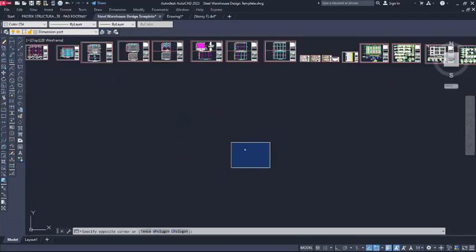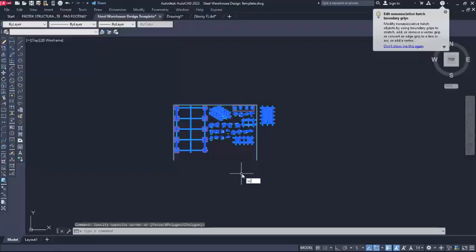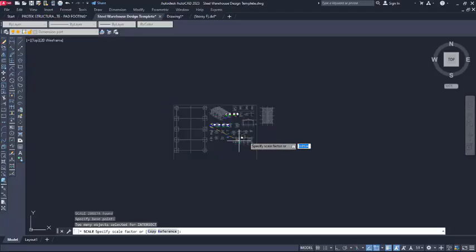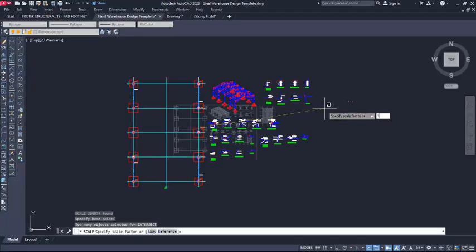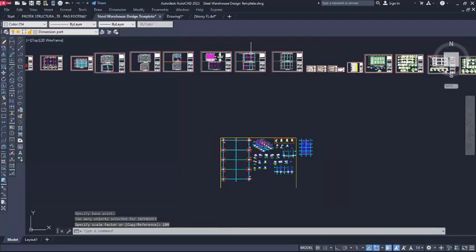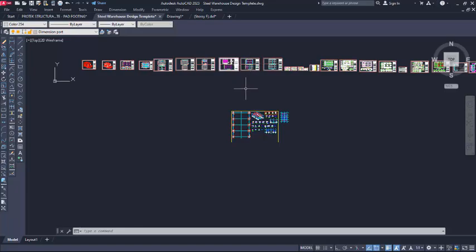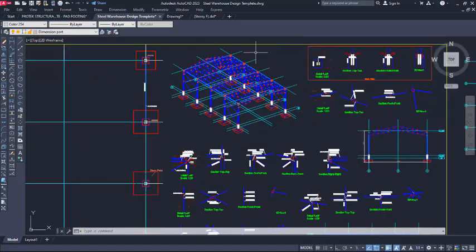So what you just have to do is get this drawing selected. After having it selected just like this, just type SC on the keyboard, enter. Having entered, pick any point right there, move your hand this way and key in 100 and then enter. Once you enter, you scale these drawings so that they can be more visible compared to this. So you can now see.